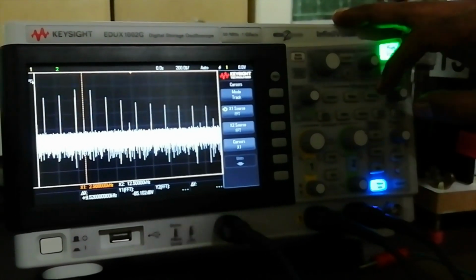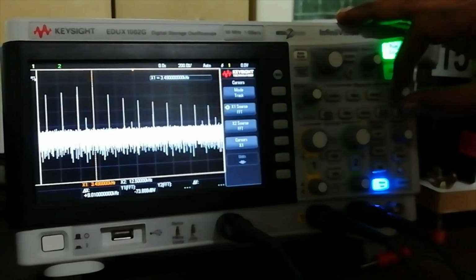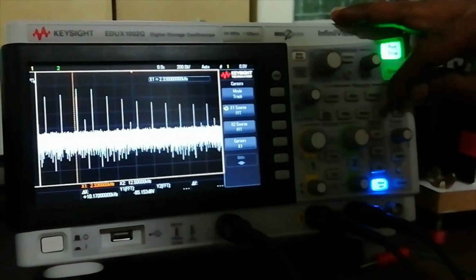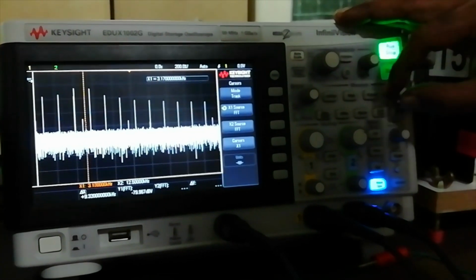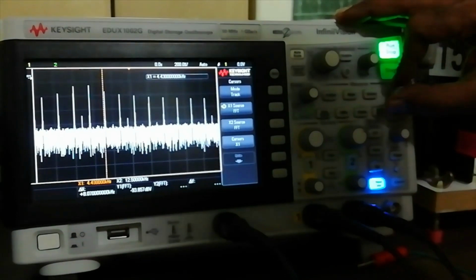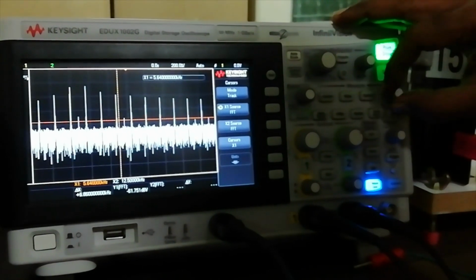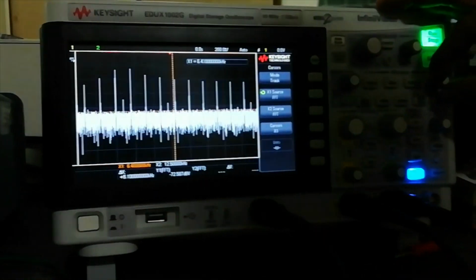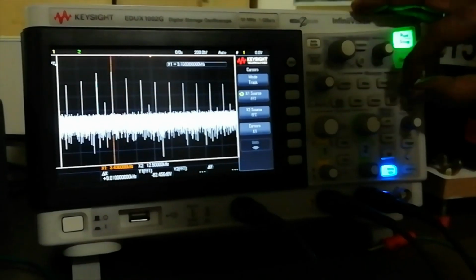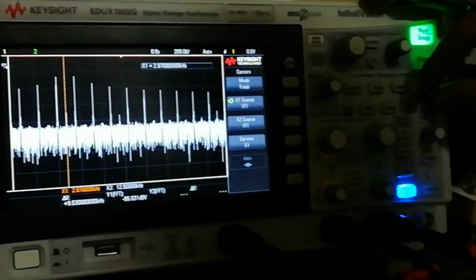Fine, this is 3, and our modulating signal is 500 hertz away, so it is at 3.5, upper sideband, lower sideband, and at the same time the gap of 1 kilohertz for upper and lower sideband is maintained at 4.5, 5.5, 6.5, but this center frequency is not very visible. If I just see, this is 3.